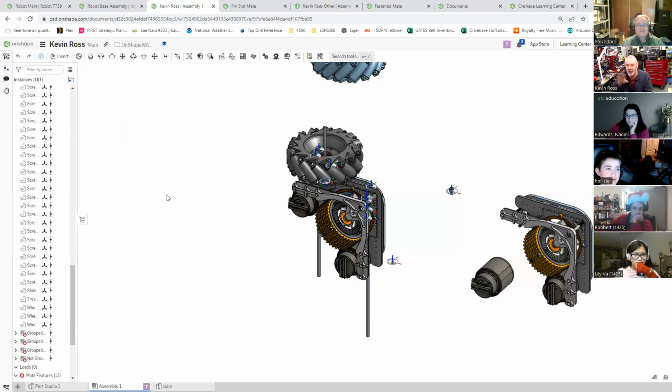There are some tricks you can do with folders and with moving sub-assemblies around, where you can take the source material for a complicated part and hide it somewhere else, so that you only get an assembly to insert, rather than getting a bearing assembly, for example, as 2 bearing races and 8 balls to insert. You can hide that from others if you think about how to structure your files a little bit.